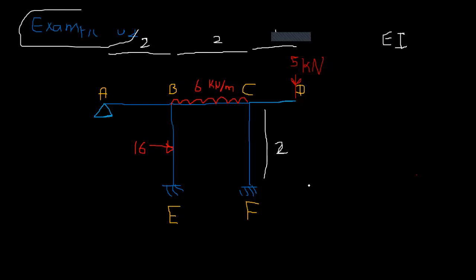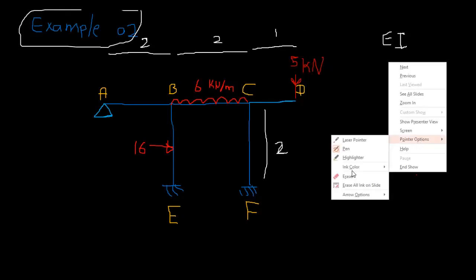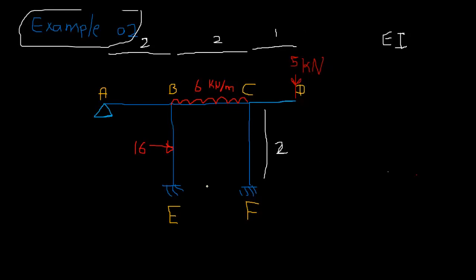So now first I need to find whether each joint is continuous, fixed, or whatever. As we discussed earlier in the video, if you see a fixed term, it is directly fixed. And this member stops here, so it has not continued over the support.